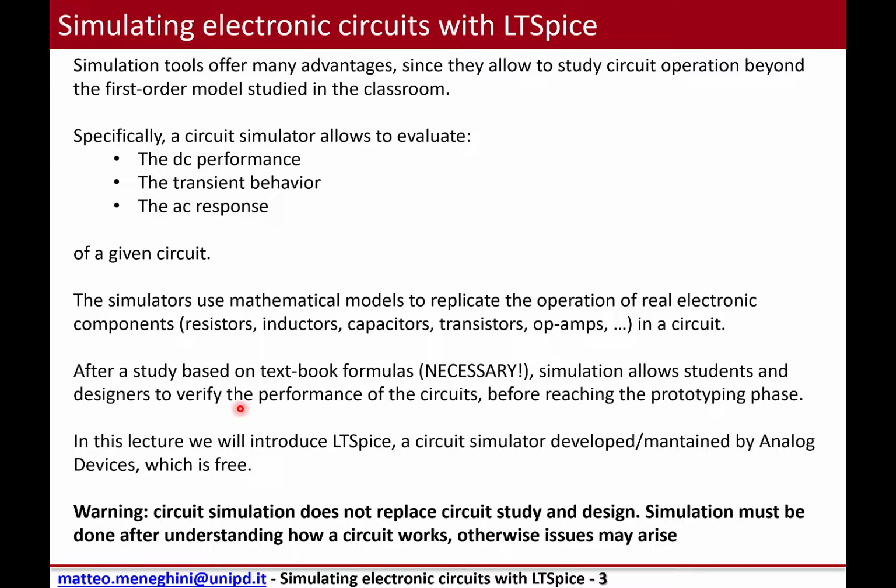So the main goal of simulation is to offer advantages, since simulation basically allows you to study circuit operation beyond the first order models that are studied in the classroom. Specifically, a circuit simulator allows you to evaluate, even on complex circuits, the DC performance, the transient behavior, the AC response, the temperature behavior, and so on and so forth.